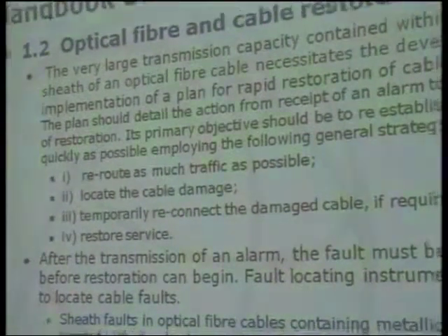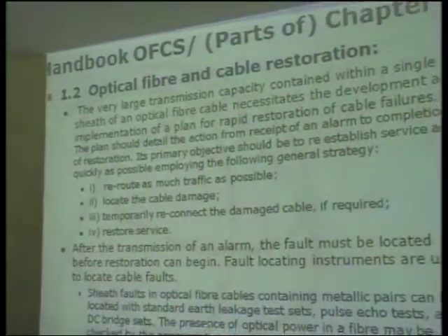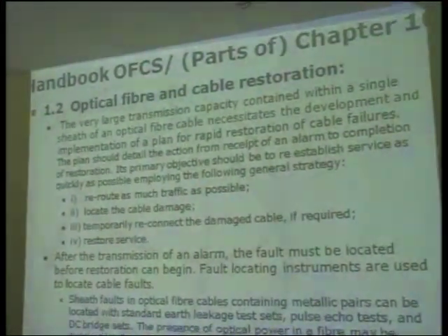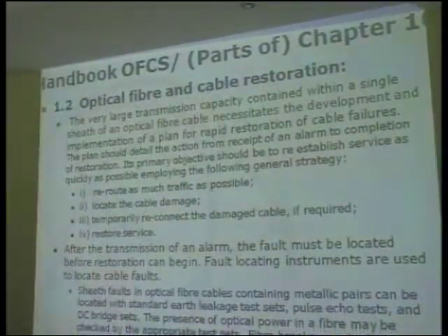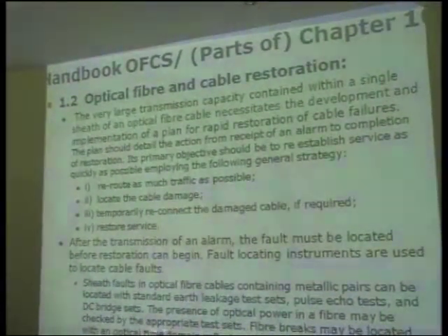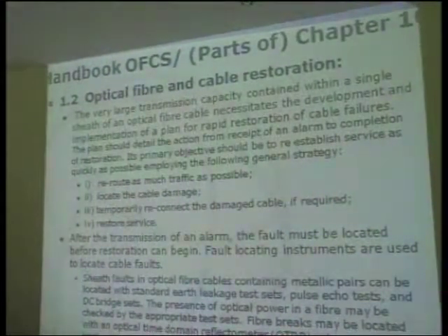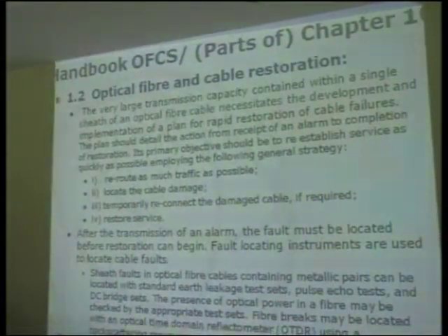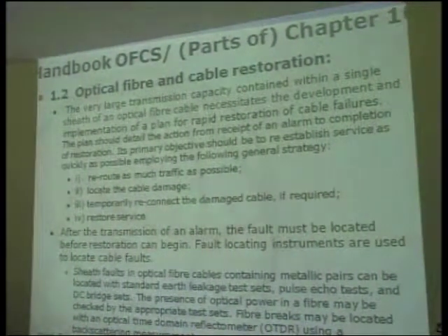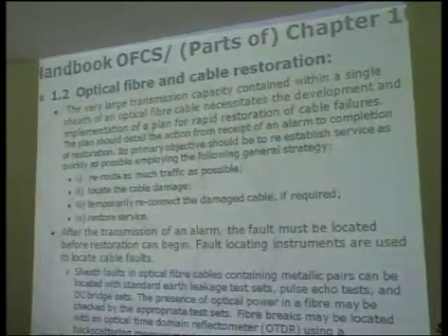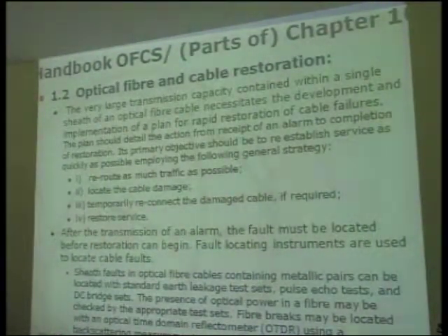And whether there is optical power or not could also be checked by an appropriate test set. But the main instrument to be used in this is the OTDR, using the backscattering measurement to identify not only more detailed information about the fault, but especially the position.